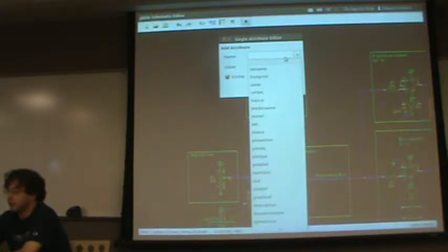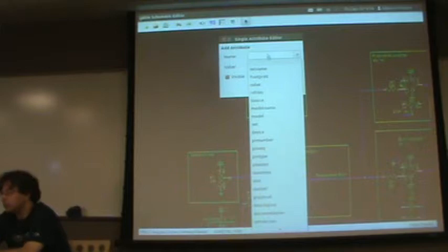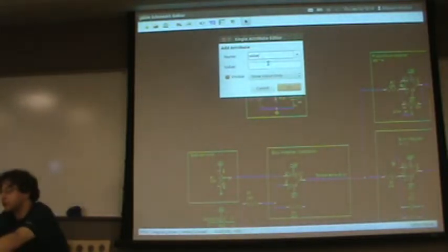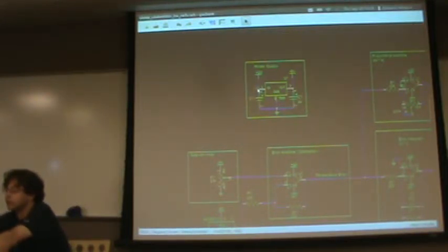Some of them are automatically set by the part itself, things like the device, you know that's a capacitor. Somewhere in this list is value, I'm just going to cheat value, and I want that to be a 10 microfarad, I just use 10U for micro, and then there it is, there's our value. You want to drag it over usually, make it actually visible.